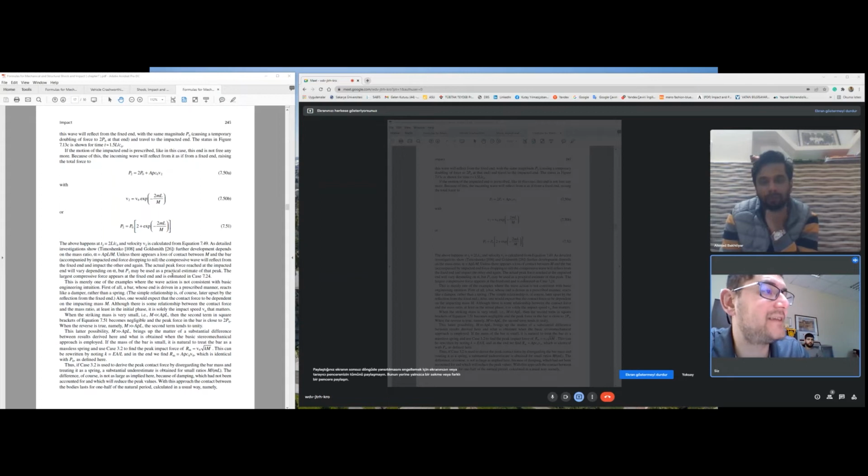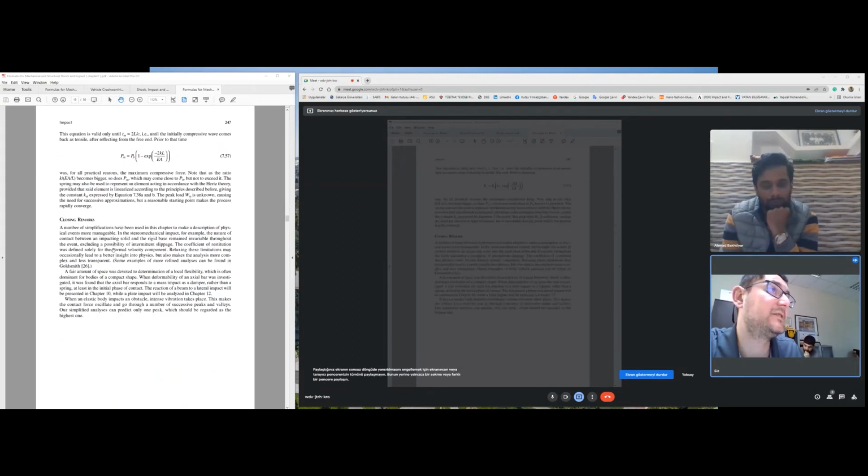You need to find that formula from the theoretical manual of LS-DYNA. When you change failure strain, what is happening? Which formula is using the failure strain parameter, for example? You can focus on that one for the initial paper. And you need to find that formula. Yes, continue.